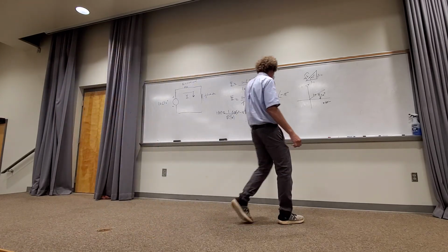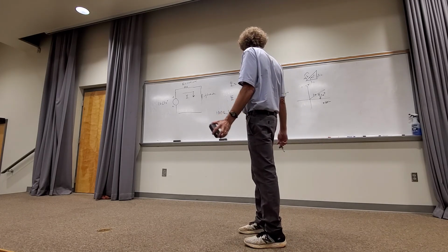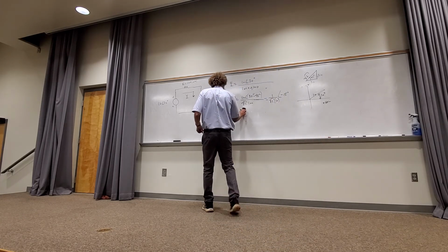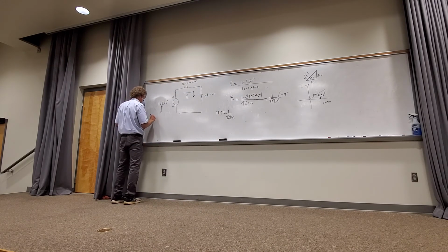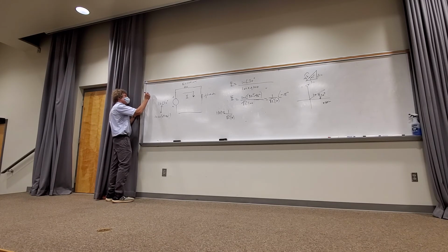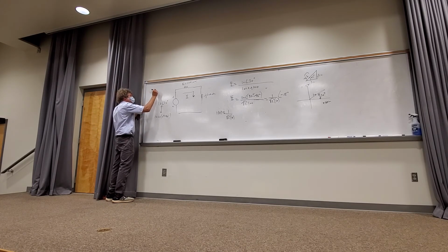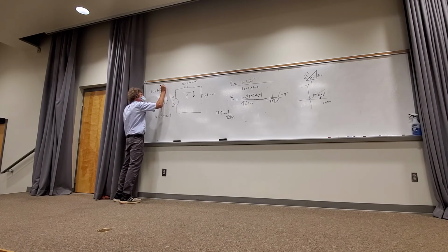Is the cosine in the numerator? Couldn't hear you. Is the cosine in the numerator? Yeah, it has to, it will vary. Remember, I said this is equivalent to really 10 times cosine of omega t plus 30 degrees. Remember that? I didn't want to keep going on this line, but really i of t is equal to the real part of the phasor we just calculated for I over there, times e to the j omega t.